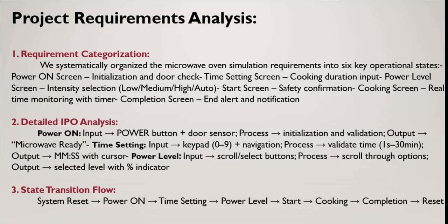It reads input signals, executes the embedded C program, and controls output devices accordingly. The LCD device is used to display system messages and output in real time. Interfacing the LCD helped us understand parallel communication between the microcontroller and output device. Input switches provide manual control to the system, allowing different conditions to be tested based on user input.